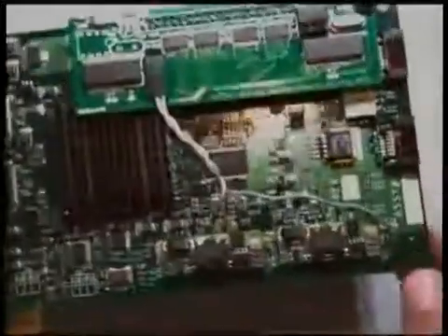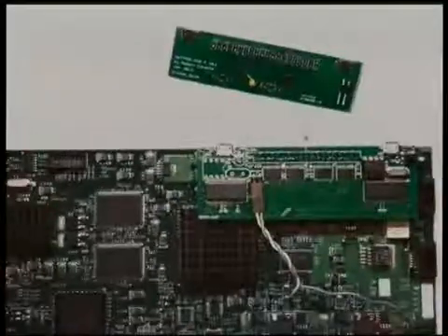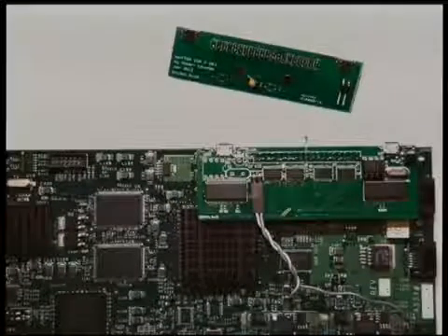These are the wires that were being referred to, by the way. These are connected to 2 points on the board where there's 2.5 and 3.3 volts power. So all the switching is in the FPGA. It's not Open vSwitch or any of that sort of stuff. This is all written from scratch in Verilog.